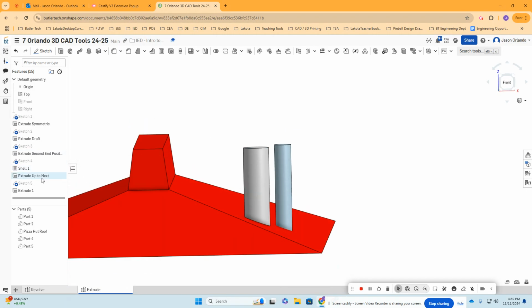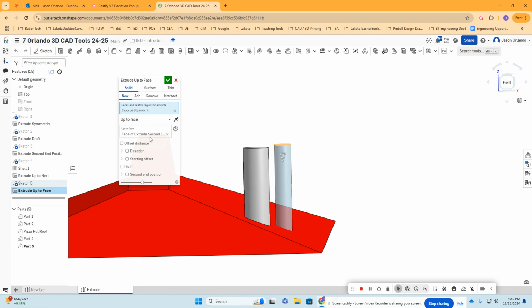So there are 2 different extrude settings that we wanted to add. Instead of using blind and a distance, up to face, we're using geometry. Now, just like that, there are some other options here where instead of using a face, you can use up to a part, a specific part in your Part Studio. You could choose a specific point, like a vertex, all these different things.